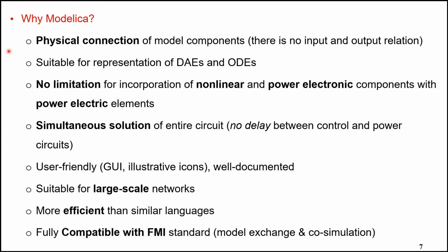Now the question posed here is why we have to use Modelica. In the previous examples, we have tried to justify the reasons for using Modelica in EMT simulations. For example, in Modelica, we have physical connection of component models. In Modelica, we can easily express the mathematical representation of dynamic behavior of the system in the form of differential algebraic equations and ordinary differential equations. In Modelica, there is no limitation for incorporation of nonlinear and power electronic components with power electric elements.